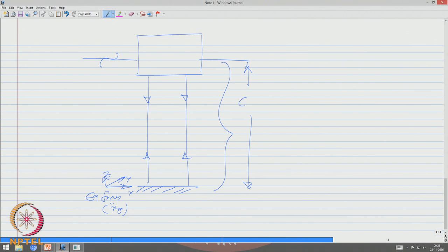Let us say the water depth is about 600 meters to as high as 1100 meters as far as TLPs are concerned. So, there is a very good water cushion, and these are only cables or tethers which are actually not any load carrying members as far as wave loads are concerned. Please understand, tendons do not account for lateral loads.